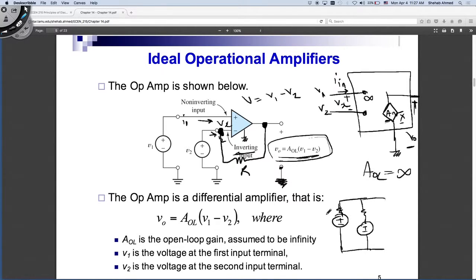There's some impedance. We will put some resistors around them. So if I have a resistor here and a resistor here, and this is some voltage V1, this is some voltage V2, do you agree that the output voltage here, which is the voltage across the parallel combination, is going to be affected by the choice of R1 and R2? Do you agree? That's exactly what we will do. We will do that such that the voltage that is being fed back to this node forces Vx to be close to 0, or 0 for all practical purposes, right?